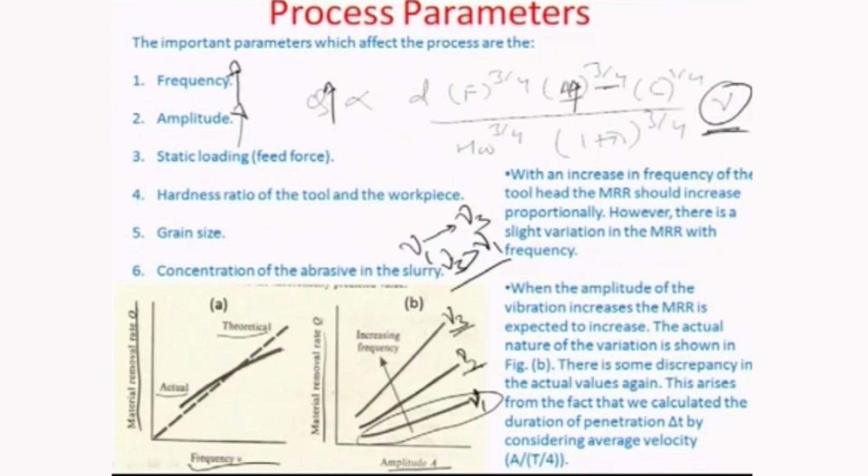So as you increase the frequency, the overall material removal rate is different for different frequencies and amplitudes, and they would have a linear increase. We have already studied this aspect, the feed force, where you saw that there is a grain crushing effect. Some other trends that can be useful are those related to what would happen, for example, with increasing amplitude and feed force.